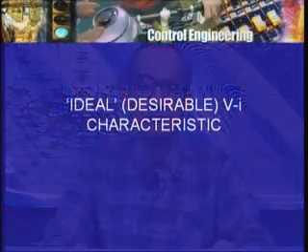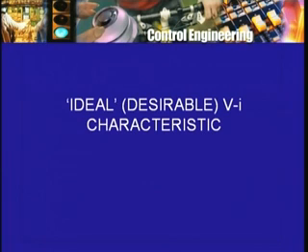Since we are talking about an electric DC motor which requires power supply for the field winding as well as for the armature winding, therefore a DC power supply. Now this DC power supply itself can be modeled under certain conditions by a simple equation like V of t, V of the source at time t, is equal to not maybe 1.5 volts DC but 230 volts DC. Now, like the RLC, this kind of an equation is referred to as an ideal characteristic.